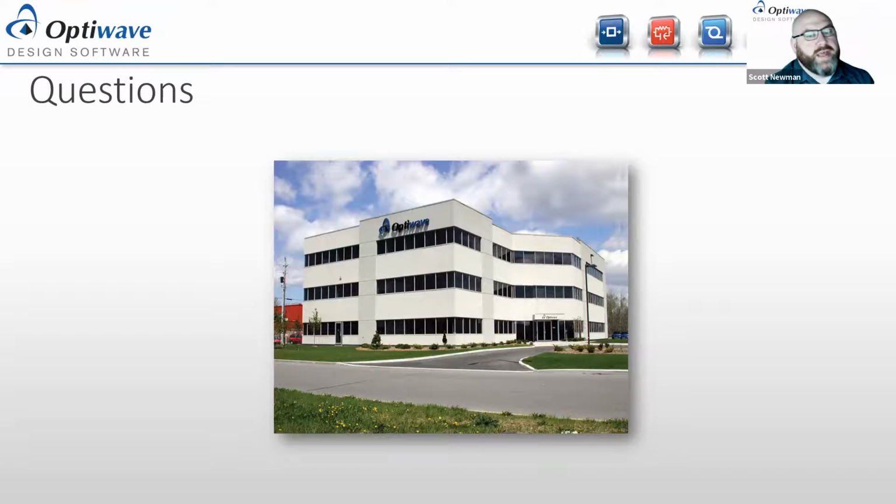So 2D versus 3D. Yes, I was doing 2D simulations versus 3D structures. So one of the tricks that gets done, at least for your initial analysis, is that the refractive index values I used for the dielectric weren't the refractive index of the actual dielectric that would be used for the structure. They would be the effective indexes. So you take a look at your structure, it's got air, then it's got silicon, then it's got silicon dioxide, and then it's got silicon again. You do a modal analysis on the vertical to figure out what the effective index is. Then you use that effective index for your calculation. It's kind of like a 2.5D simulation.